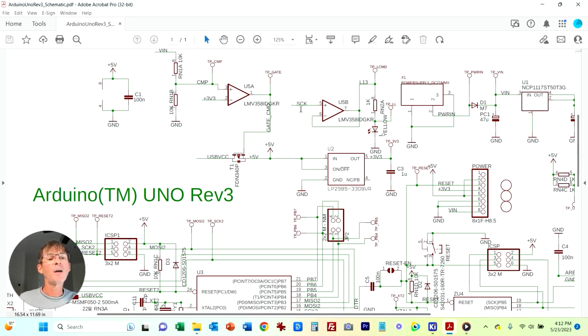And they didn't want to drive that directly from that pin and load that pin, because that's a clock signal that's being used. You don't want to load that down. So this buffer basically buffers it. So this output can drive a lot more current without impacting the input here. And that's the purpose of this little circuit here. So it's the same op amp used for totally different purposes. This is actually a digital application, and this is an analog application of it.